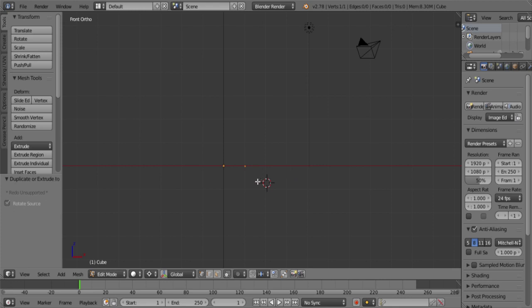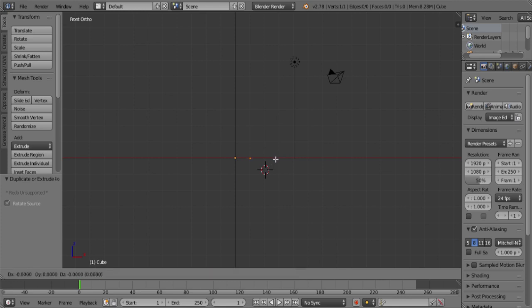When I zoom in, you can see more refined grid lines appearing. If I press G and hold down control, it's pretty clear I'm moving in steps of 0.1. Below on the left, I just right click and zoom out until those more refined grid lines disappear, and now I'm going to press G again and hold down control. Now I'm moving in steps of 1. I right click to jump back. So the more you zoom in, the more refined your steps will be.